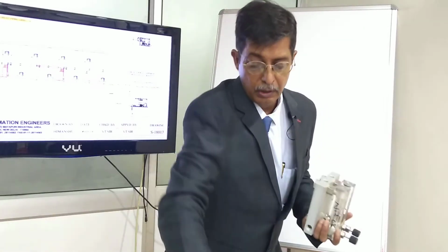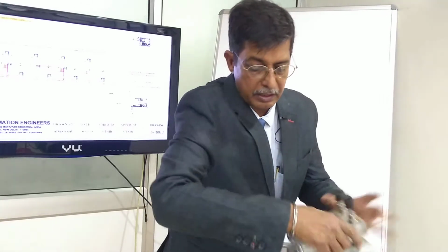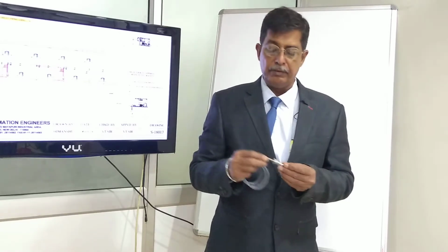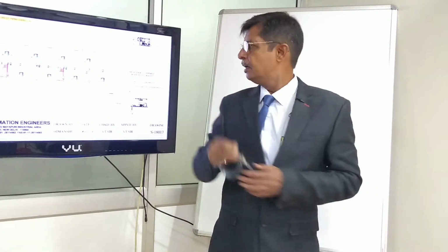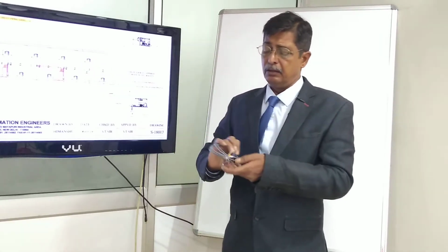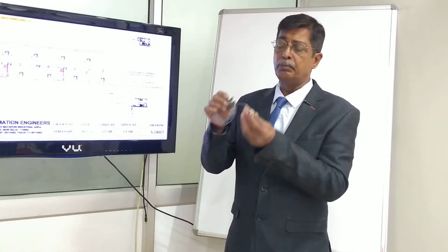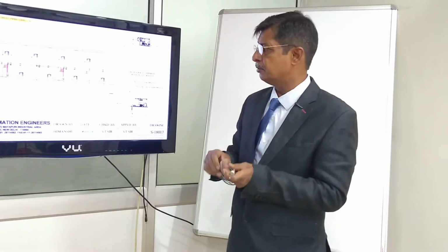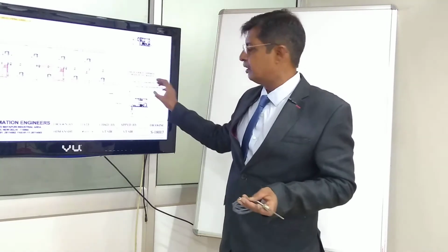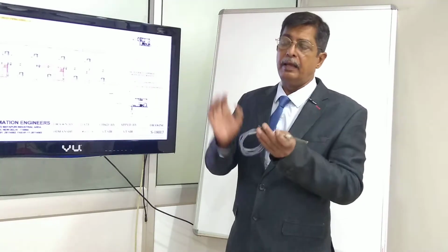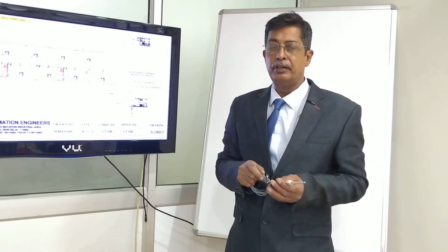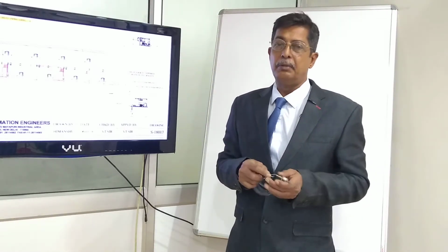And of course, even though the probe is not really an expensive proposition, if we have too many of these, carrying all these wires right till the control panel and monitoring the temperature of each bearing can be a bit of a daunting task. So it may not really be required or necessary for most applications. I would only suggest it in very critical applications.